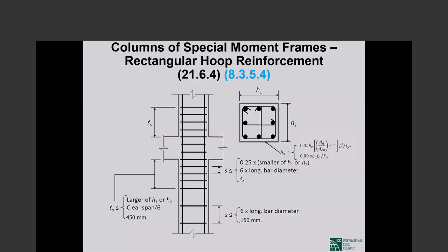It happens to be the same piece of reinforcement. It serves two purposes. When we try to figure out if it is sufficient for one purpose, we use f sub yt of up to 100 ksi. When we try to figure out if it is sufficient for the other purpose, we use f sub yt of 60 ksi. There is no contradiction that I see.